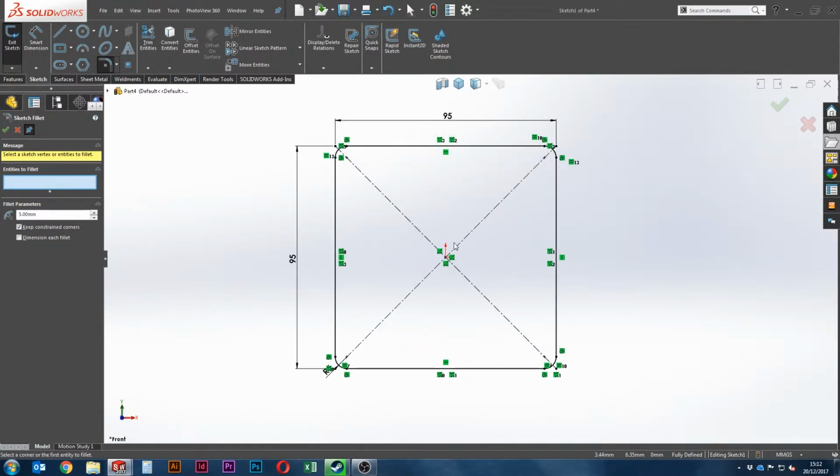Now the key thing to realise with weldment profiles is when you create them, the origin, shown here, is the initial pierce point. So whenever you select your weldment and select your sketch profile for the weldment to use, it's always going to default to the origin. And in quite a lot of cases, you don't want it to default to that origin. If you're using, say, circular hollow section in steel, you may want it to be on one of the edges.